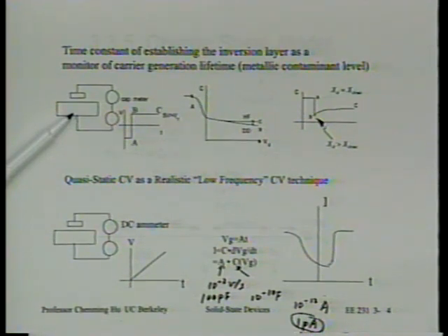We often suspect the oxidation furnace can be dirty or diffusion furnace can be dirty. Sometimes we even suspect clean can be dirty. But when they're dirty, we don't have a convenient way of detecting this contamination. Turns out the most convenient way, not very quantitative, but almost the only convenient way, and therefore often used, is through some kind of capacitance measurements.